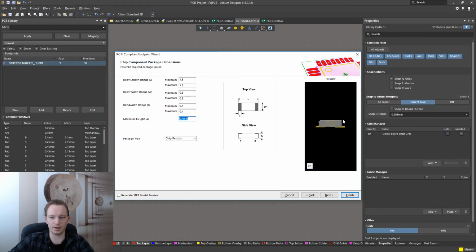You don't want to have the pads like outside, or not completely covering the actual pad on the component. If you look at this picture here, what's going to happen when you start soldering it is that if you have solder here and you start heating it up, it's going to drag the resistor to this side. So the resistor is going to lose contact with this pad if you have any space between the end of the pad and the end of the actual connector on the resistor. So that's going to be a pain to solder later.